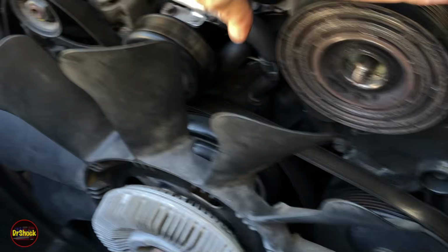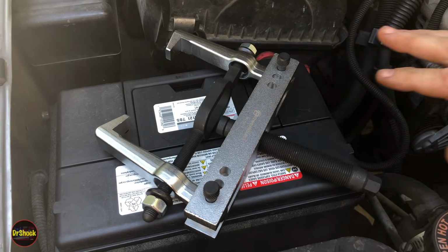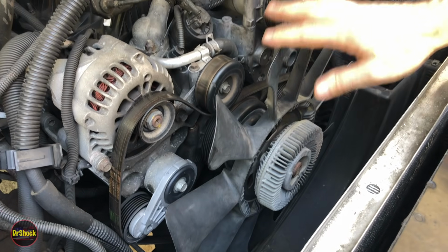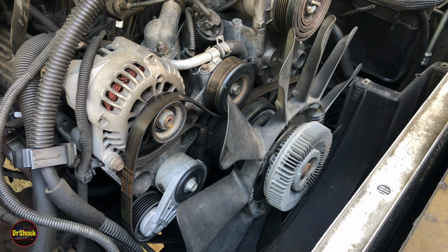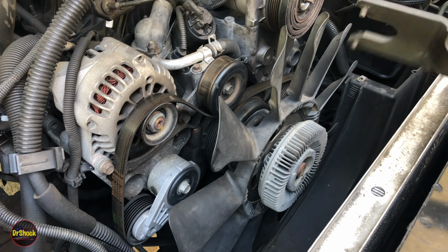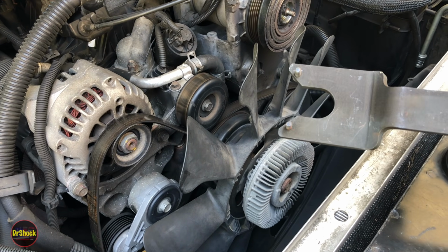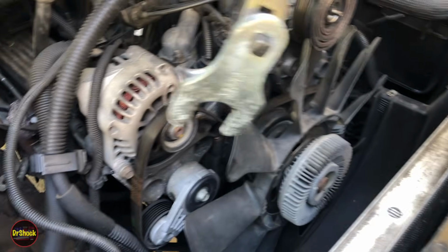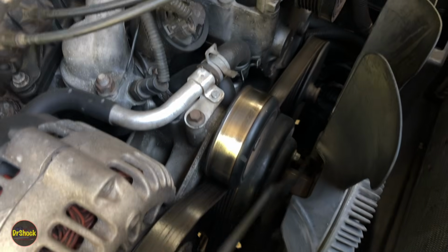All right, now to get this off, we're going to have a puller. So let me go get the puller and we'll remove this pulley assembly. All right, guys, the particular tool that I have is an aftermarket compressor pulley puller. The fan's in our way, so I'm going to have to remove that. Depending on the tool you use, you may or may not have to do that. The fan on this particular engine and series truck has some holes in the pulley, and this tool is designed to sit in those holes and hold it steady, while this tool we're going to come in and turn the nut.